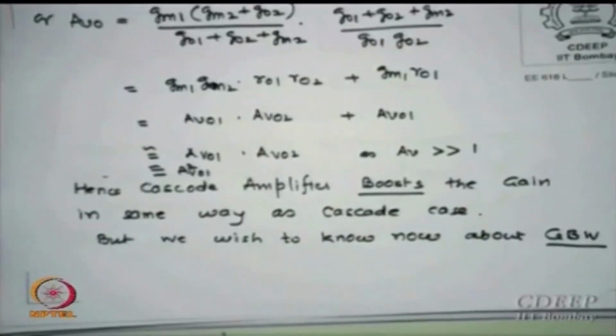The point I was trying to make is essentially that a cascode single stage is not very great compared to a two stage cascade, because we are comparing all the time with why not connect two amplifiers in series, which is done in many places. So what is this cascode actually doing?